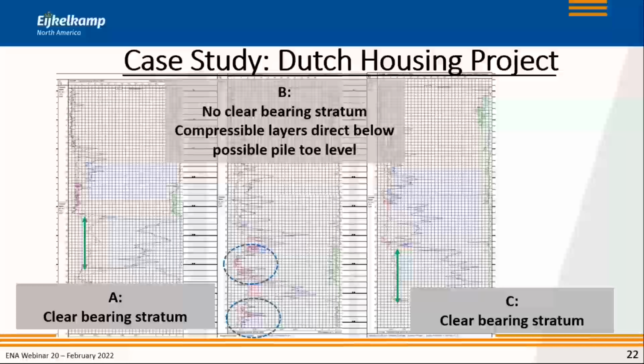And that's why I strongly believe in doing a CPT and not necessarily having that many test piles. As a matter of fact, in the Netherlands, quite often you don't even do a load test on a pile. You basically do more extensive soil investigations, and on the basis of your CPT, you trust that the pile has the right capacity.